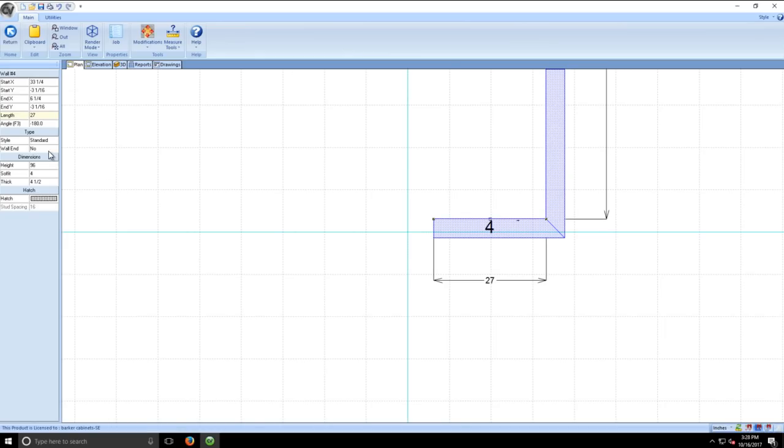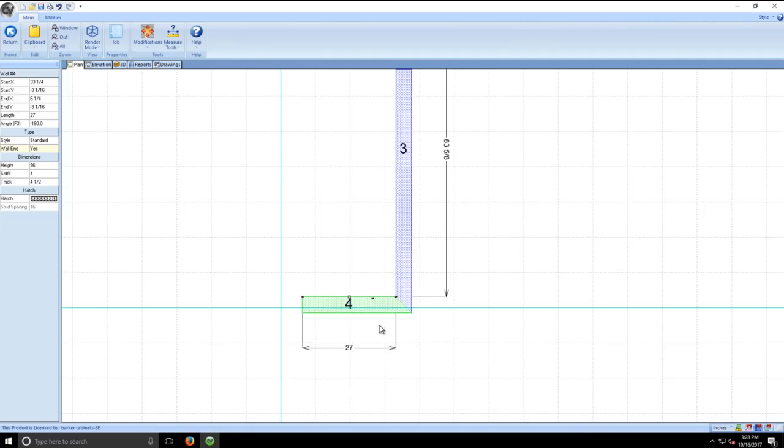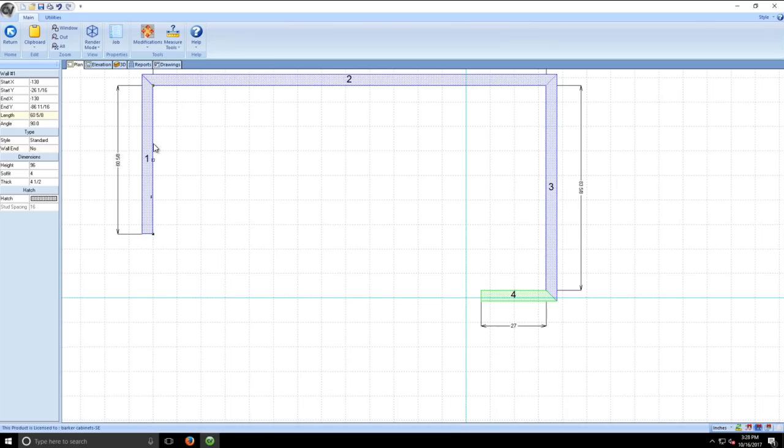To do a wall end, just go over here and click this little box. It's going to turn it green or whatever color you have the template set for. And what that's going to mean is it stays out of the way. It doesn't try to push your cabinets off. This thing will try to snap your cabinets into place, and sometimes it'll keep them like 12 inches away from the wall and whatnot. So just put it as a wall end. Technically, it's not the end of the world if you left it like that.